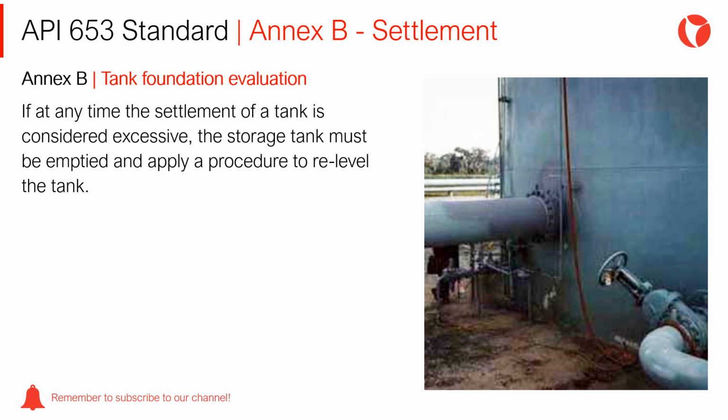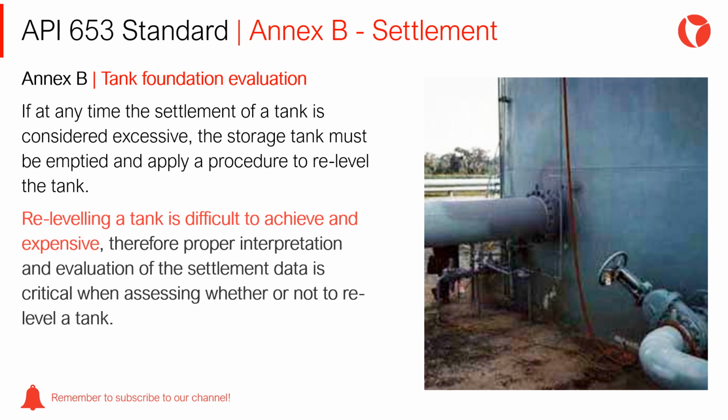If at any time the settlement of a tank is considered excessive, the storage tank must be emptied and a procedure applied to re-level the tank. Re-leveling a tank is difficult to achieve and expensive. Therefore, proper interpretation and evaluation of the settlement data is critical when assessing whether or not to re-level a tank.